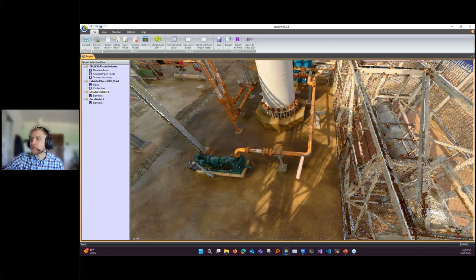Let's see, Civil 3D. I'm not super familiar with Civil 3D export options. We do have a ground surface model that's built in, that's been there for a long time, and it only works with structured point clouds from terrestrial scans, but it can do a LandXML file. Outside of that, STEP is probably the only thing that would really go to Civil 3D. Is it just kind of a stock geometry export, if you want to represent some basic stuff?